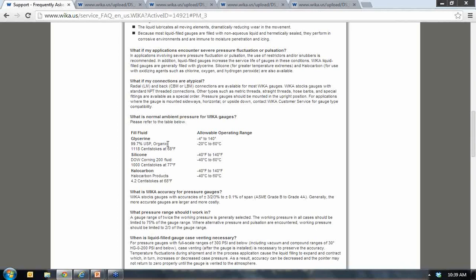The solution is the mini siphon. Its smaller package reduces the need to wrap it to prevent operator contact, and it gets used in the same way by creating an airspace above or below the gauge and above process to prevent temperature and pressure spike. It's a great option, and we've had tremendous success with that where it's been used. Good answer.